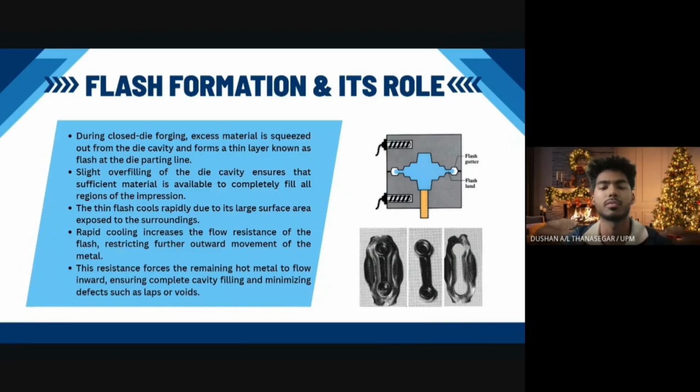This overfilling of the material is actually beneficial as it ensures that there is enough material available to fill all regions of the die impression, especially thin or complex sections. The flash itself is very thin, which means it cools rapidly due to its large surface area being exposed to the surroundings, as you can see here. As it cools, it becomes more resistant to further deformation.